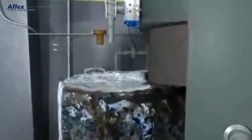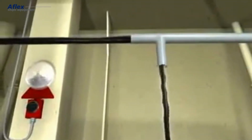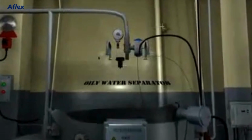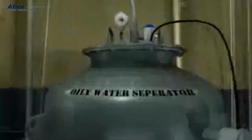In case oil is detected in the inlet chamber sensor, the valve on top automatically opens and the oil is directed to the separated bilge oil tank. The bilge pump is running during this transfer. In case the oil content in the bilge effluent is high, the same will tend to rise in the main chamber. Once the oil is detected in the sensor here, the following operations are carried out simultaneously.